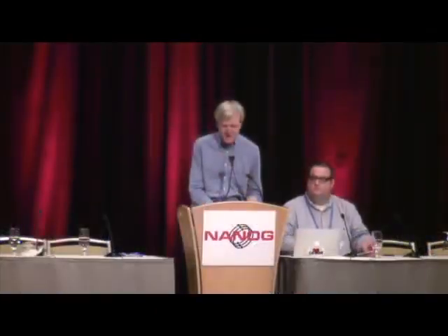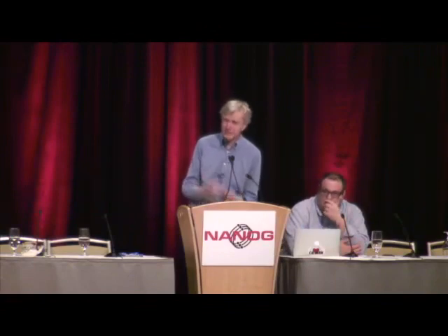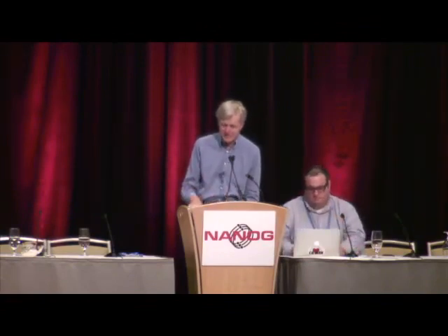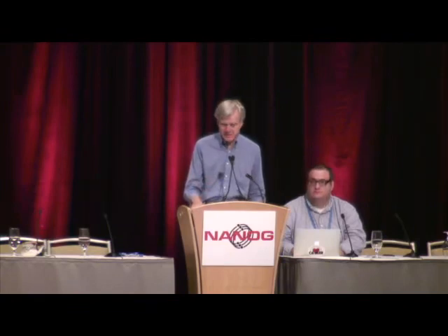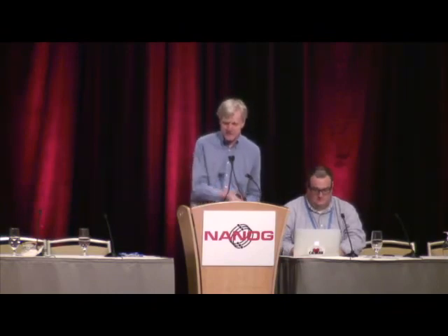Yeah, that's a very good point. ASIC design is much cheaper than full custom. So in the ASIC world, I don't know if I have absolute numbers here, but it's probably a quarter of the cost and effort compared to doing a full custom chip. And part of this is how many chips are you ever going to make? How many chips are you going to sell? So full custom has been applied to the higher volume opportunities, and if a router has so many chips but the company only sells so many routers, you can't actually quite justify it. So this is a trade-off in design cost versus optimizing on the silicon side.